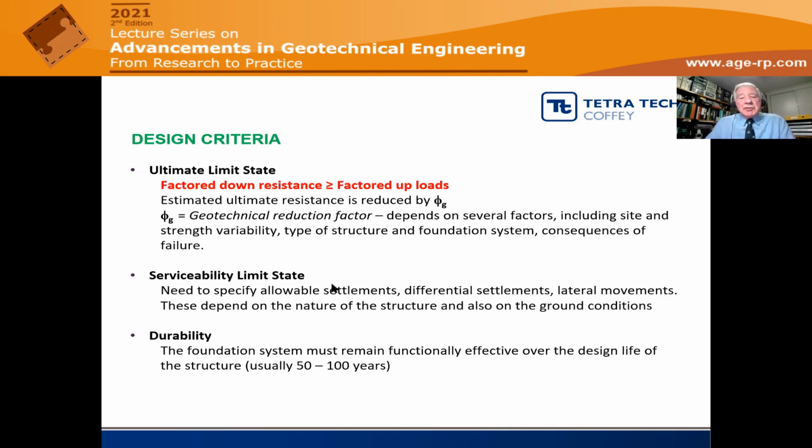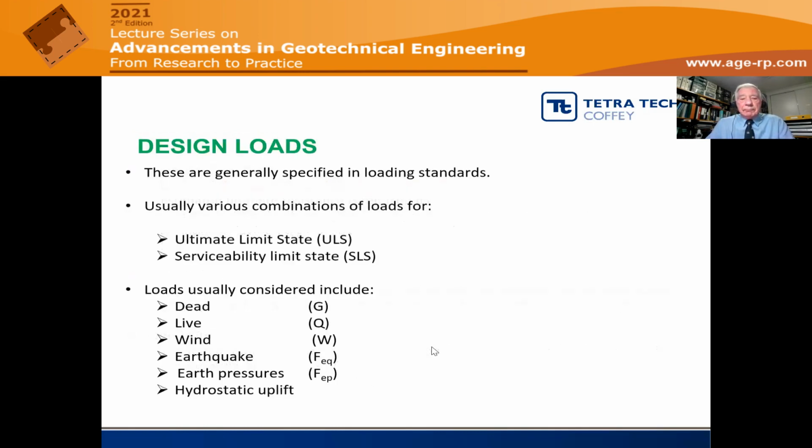In terms of serviceability, we need to specify allowable settlements and differential settlements, possibly lateral movements, and these depend on the nature of the structure and the ground conditions. And as I mentioned earlier, durability is increasingly important, particularly for structures that support marine facilities, where we need to make sure that we have durability over an extended period of time.